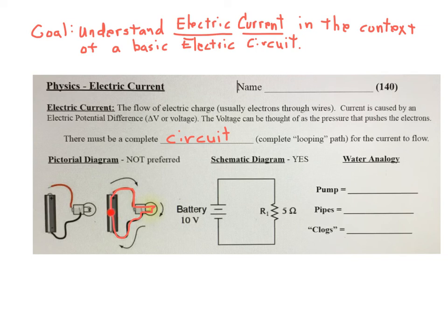The electrons that are here start moving up this way. Actually, technically, this is the negative side of this battery. I think it's labeled, yeah. The electrons actually start here and they start going this way. The electrons go from the negative and they go through this wire, and there's electrons everywhere, pushing on each other basically and rotating just like in musical chairs. When they go through this filament, there's a lot of friction here, and it causes heat and light. This filament is usually tungsten. So now the arrows here, and I'll make note of this later on, give you the direction of what's called conventional flow.